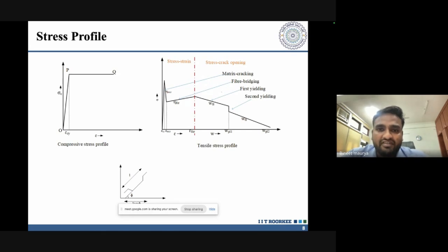But after the first crack, the stress carrying capacity decreases. When fiber comes into the picture, it tries to bridge that gap and reduce the crack propagation. Still, we can apply the stress-strain approach because there is no clear crack opening. Up to the end of the bridging point, after that the fiber pull-out will take place, meaning a clear crack has occurred. Of course, it is not traction free. There are fibers bridging, and they are trying to resist the crack propagation.